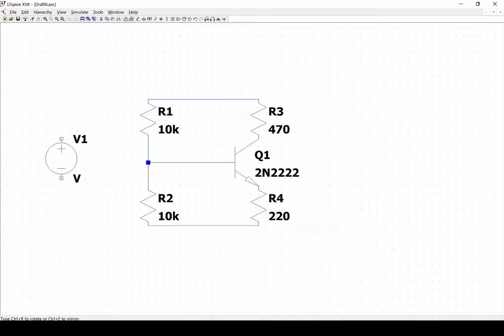So for instance, I will put this here. It's called the voltage supply V1. And then if I press F3 or if I click here on this wire button, I can connect electrically the voltage generator to my circuit, positive and negative terminal, as you see over here.